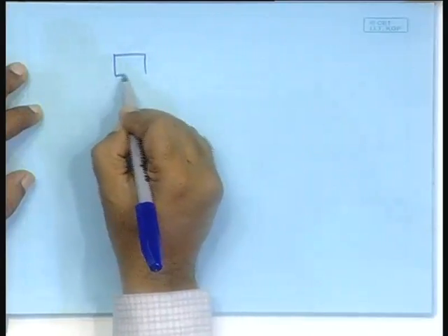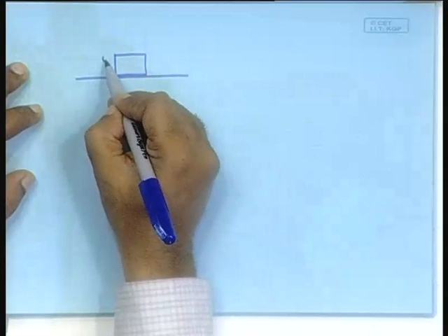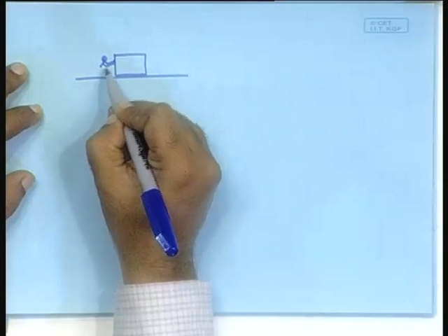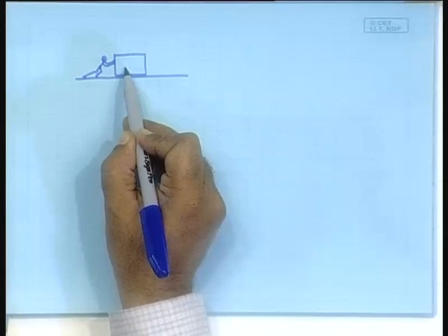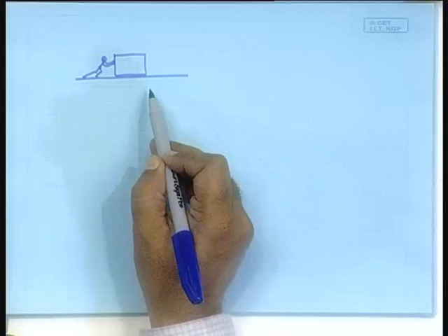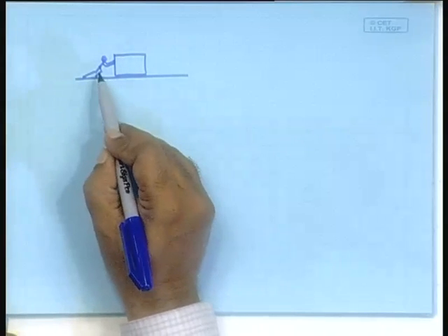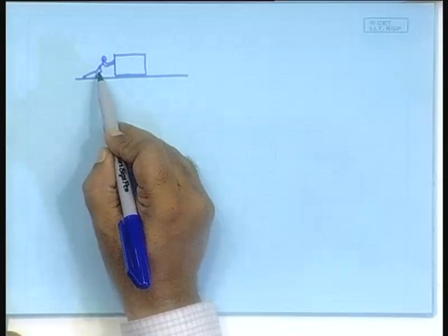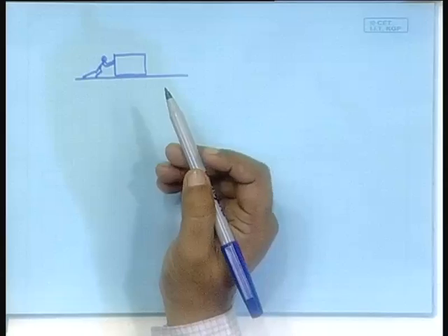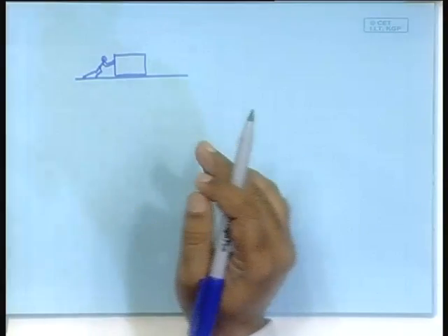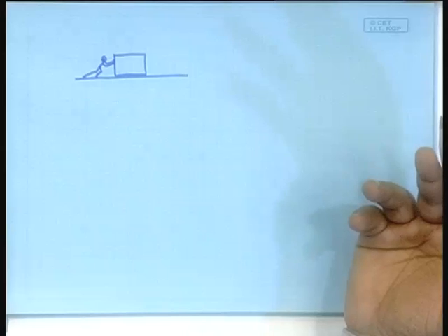Now, notice there is a mass and say some fellow is pushing it like this. So, this is the SE element and this mass is the inertial element I. So, this system, how will you represent that? Notice that these two, the SE element and the I element, have to share the same flow. Otherwise, it will go off his hand. So, the contact is lost.